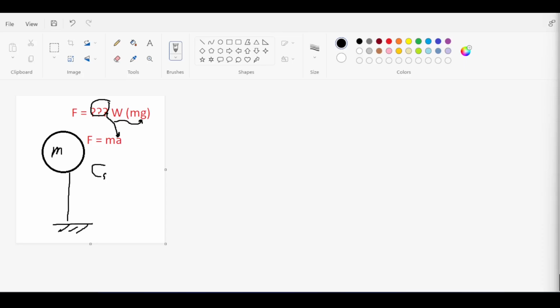Now, this equation is found in the ASCE code under section 12.8-1 if you have the ASCE 2016 code. And the equation here for CS is also defined in 12.8.1.1. Now this is highly technical, but I only want to give you the gist of it. This CS is actually SDS, a factor I will explain in a moment, divided by R over the importance factor I. Now what is SDS? SDS is the design spectral response acceleration, R is the response modification factor, and I is the importance factor.